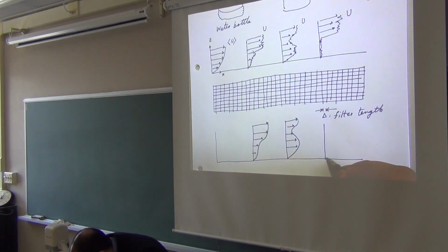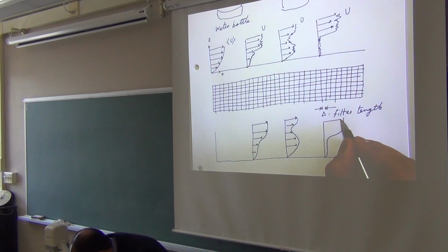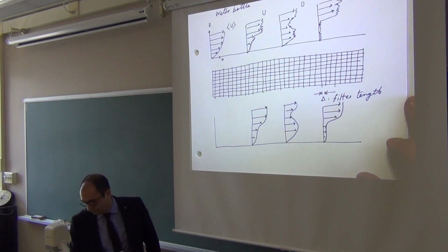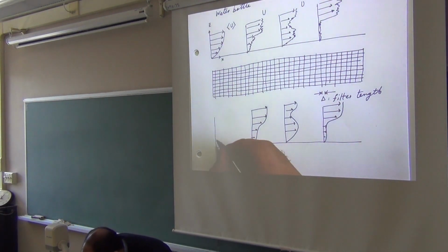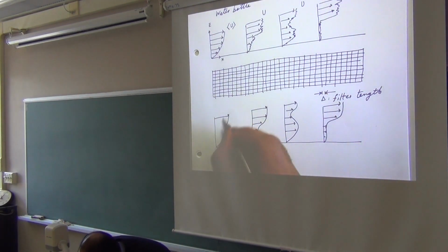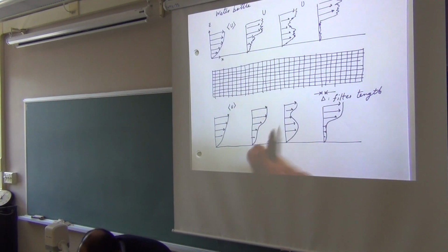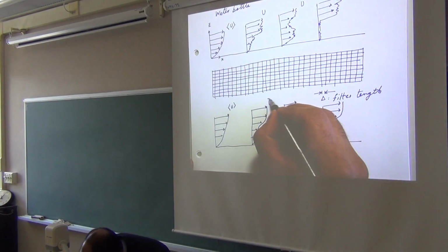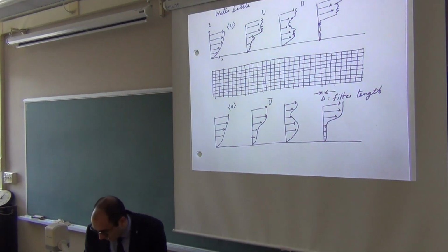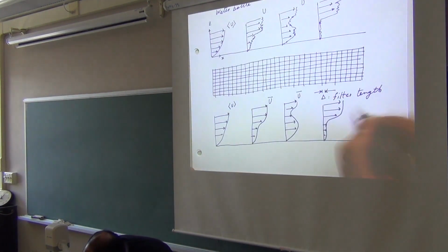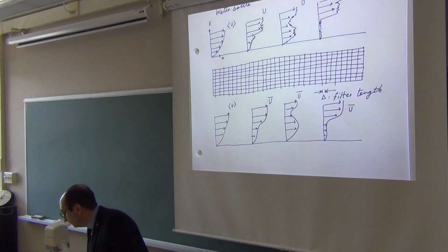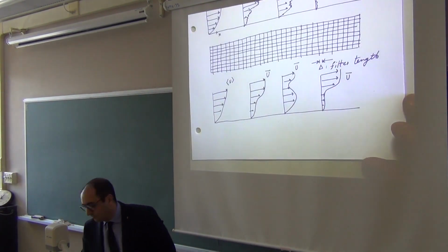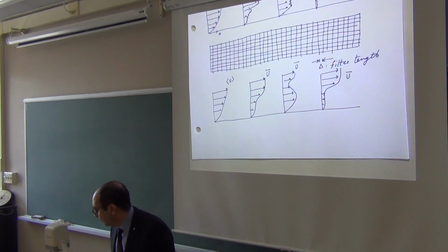This one would look like this. So this would be, still the time average the same, but your simulation is no longer steady, right? It's transient. From moment to moment, the large scale field changes. So if you like, this is now U bar at different time instances. And in the terminology of large-eddy simulations, we call each one a realization.